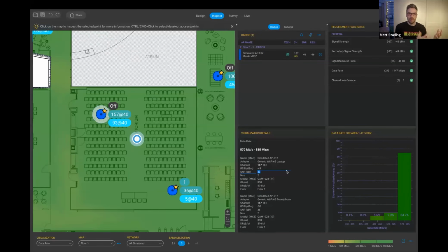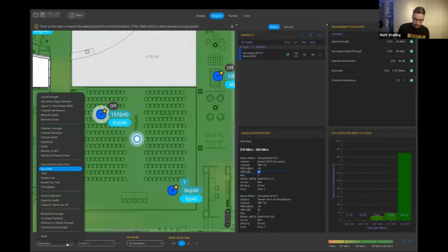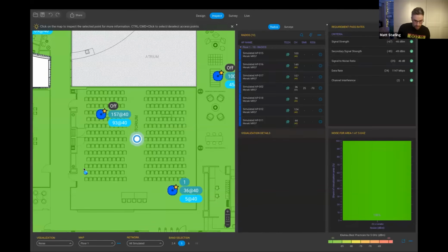And when you double something in Wi-Fi, effectively you have an increase of 3 dB. That's why we're seeing this SNR value go down. And if we take a look at the noise value here, you will notice that the noise floor has now gone up by 3 dB.